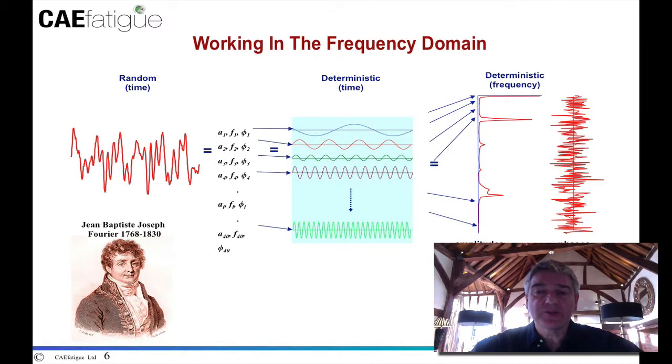So let's ask the question, what is the frequency domain? For this, we can begin with Fourier series from the early 1800s. Basically, Fourier series methods assume that the time-based signal can be transformed into a form which is a function of frequency as shown. In general, this is a much more versatile form of showing the loads. Of course, there are some restrictions and assumptions, and unfortunately these have been allowed to severely restrict the use of the techniques for structural analysis and fatigue life calculations.